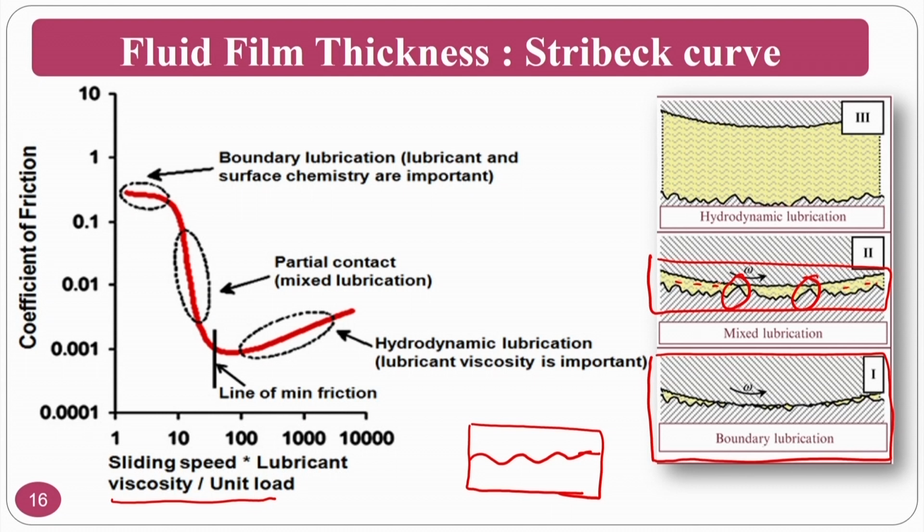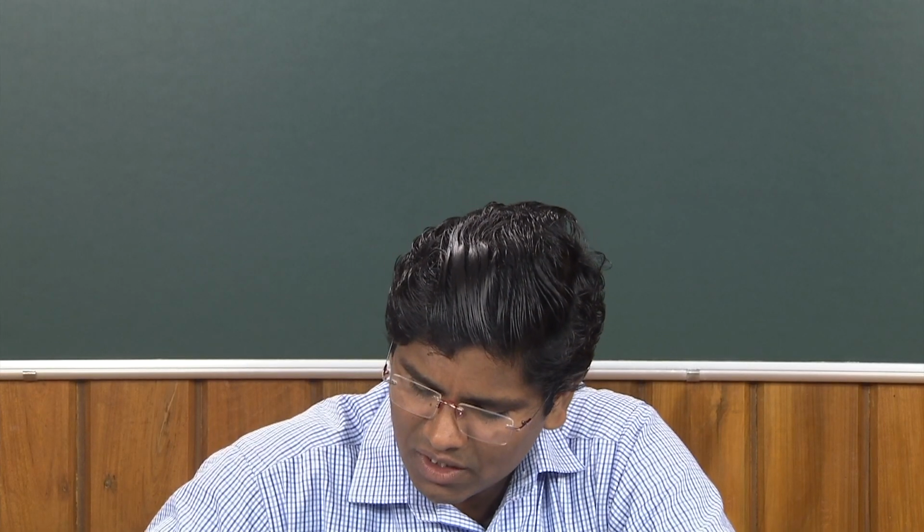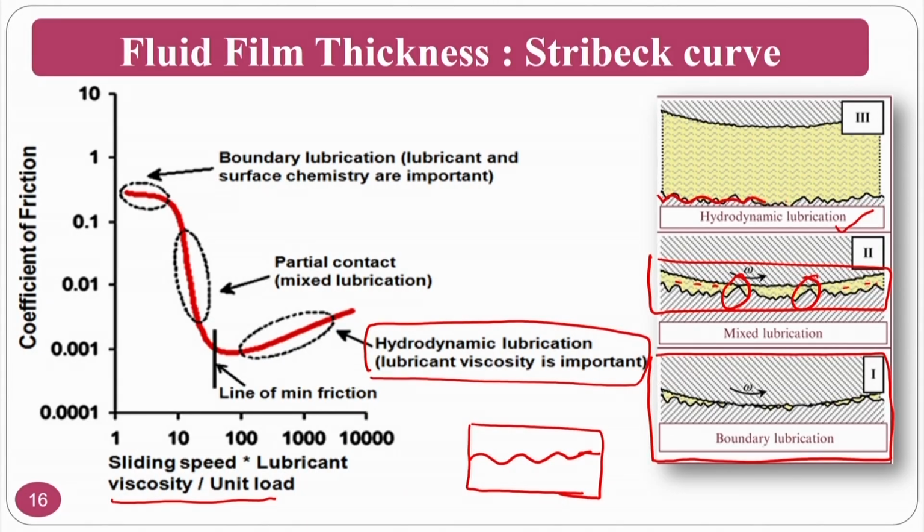In the hydrodynamic lubrication, that is nothing but where you do not have contact, no contact. That means elastic emission machining works in the hydrodynamic lubrication region, where your workpiece is at the bottom and your tool is at the top. You do not have any contact, and you place the abrasive particles there. Okay. So these are the abrasive particles along with the carrier fluid.